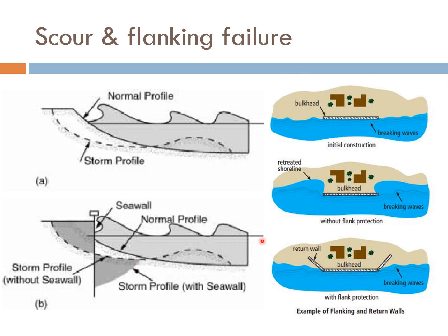This figure here on the right shows effect of flanking. If this is a coastline where only this part of the shoreline is protected, then there is a potential possibility that the up coast and the down coast may be eroded. So it is very important for the ends to be designed properly with end wall or proper tie-in.